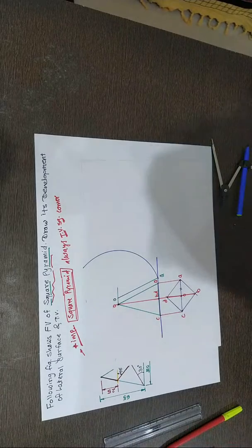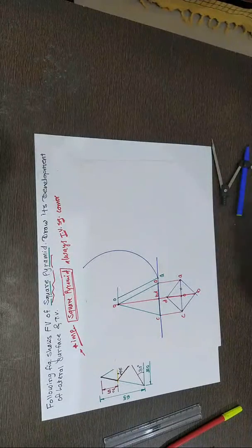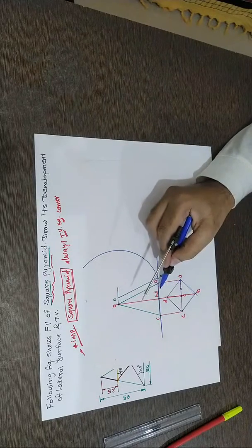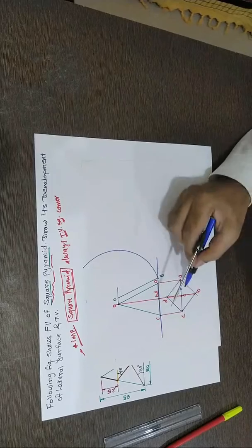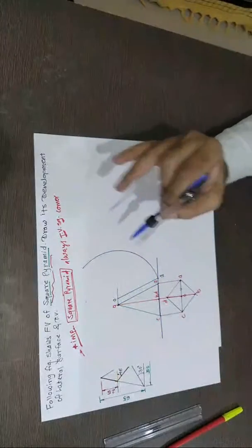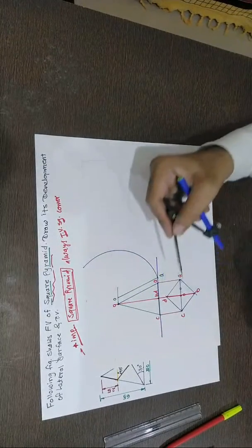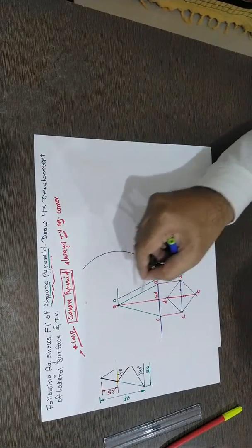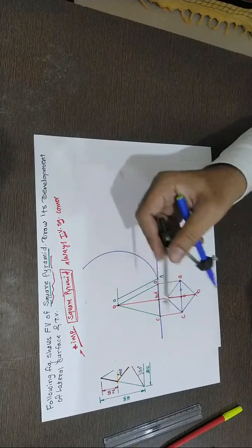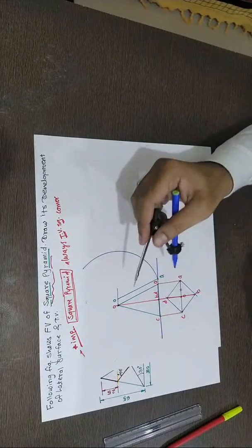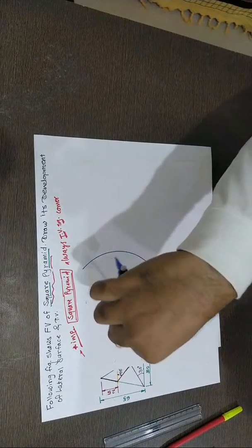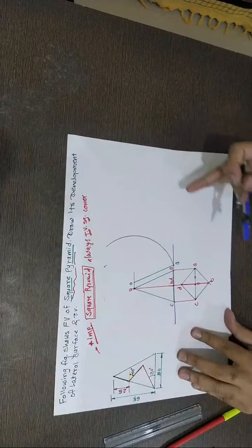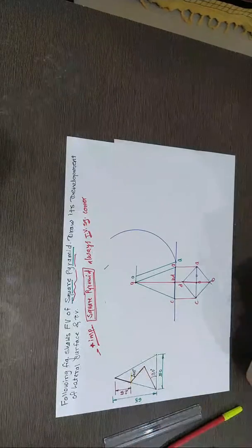So I just explained OA should be parallel to XY, this horizontal line, then only this slant edge represents the true length, means actual what you can see and what I have drawn. So parallel to OA, draw one more OA here, means you can see a replica of this, same as it is, and with OA as radius, draw one arc. So I have drawn the arc. Remember, still I have not completed the front view, I need to mark those things.